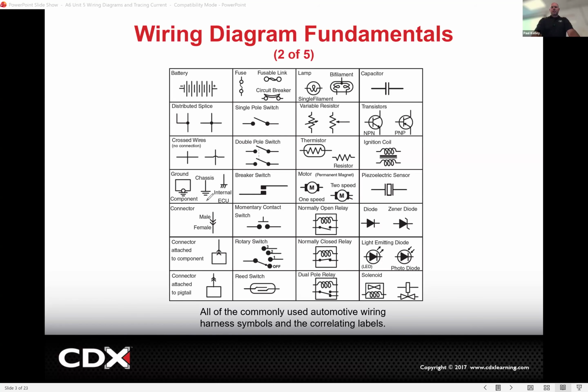So there is a way to actually test the component ground, and you test it very similar to a chassis ground, but rather than testing the wire, you actually just put your lead right on the component itself and see, does that have a good ground? So if it's a good ground, it should have 0 volts. The way I would test it is I put my red lead on the positive battery terminal or a known good 12 volts, and then I take my black lead and I just touch the housing of the starter. And if I read 12 volts on my meter, that shows me that there's a good ground there, right? Because my red is on a known good positive. So if my black lead is on a good ground, it would read 12 volts. That's a good way to test it.